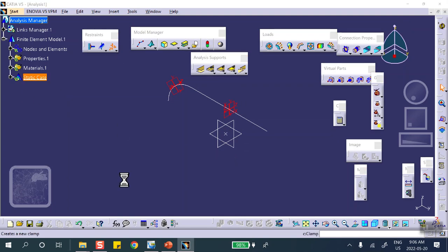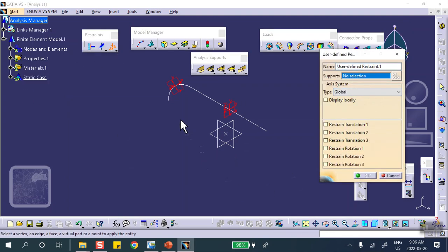User defined restraint. Let's clean this up so that we start fresh right there. No displacement in direction Z, rotation opposite. So if this is checked, this must be free. If these are free, you can see they are free. These must be checked. No part marks for that point. Okay? Let me give you an idea. If this problem was given to you, I would say 20 marks. Having correct restraint would be what, 4 marks? No part marks. Okay?